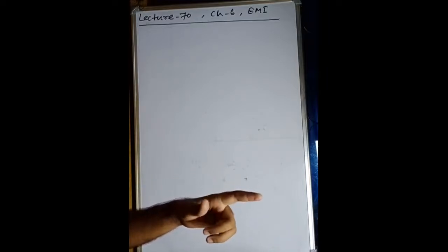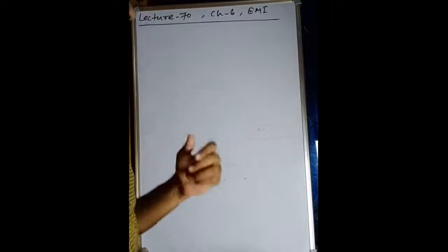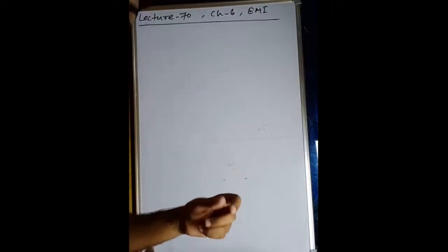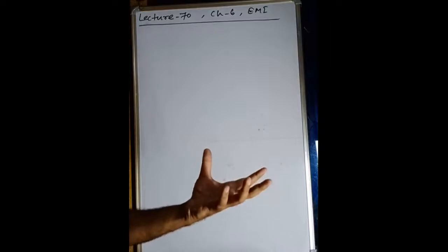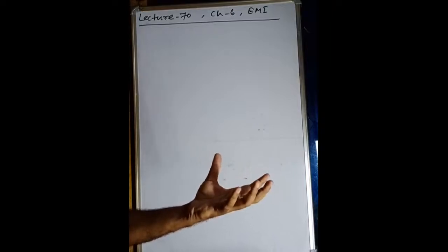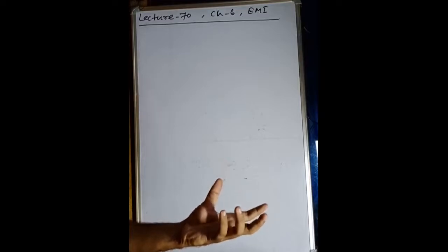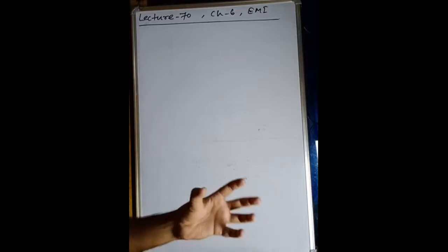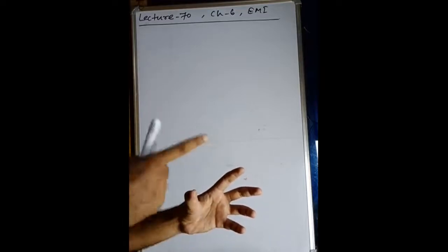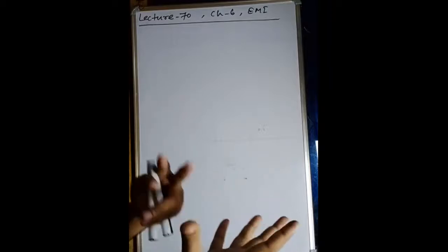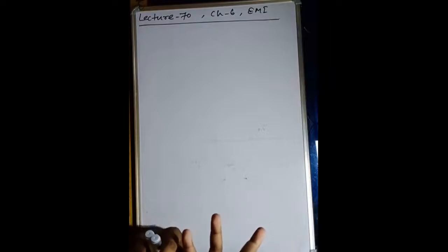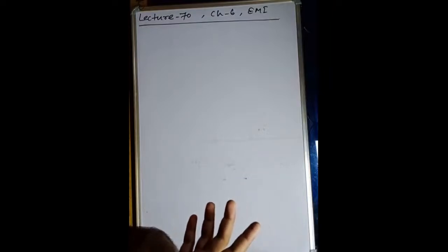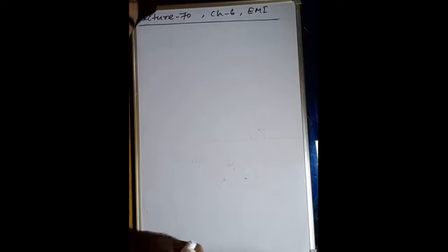That was self-inductance. Here in mutual inductance, we will have two coils. One coil will change the current, and due to that change in current, the magnetic field will change. That magnetic field lines link with another coil, and that other coil will experience a change in magnetic flux and start inducing an EMF, that is the back EMF, and this phenomenon will be considered as mutual inductance.